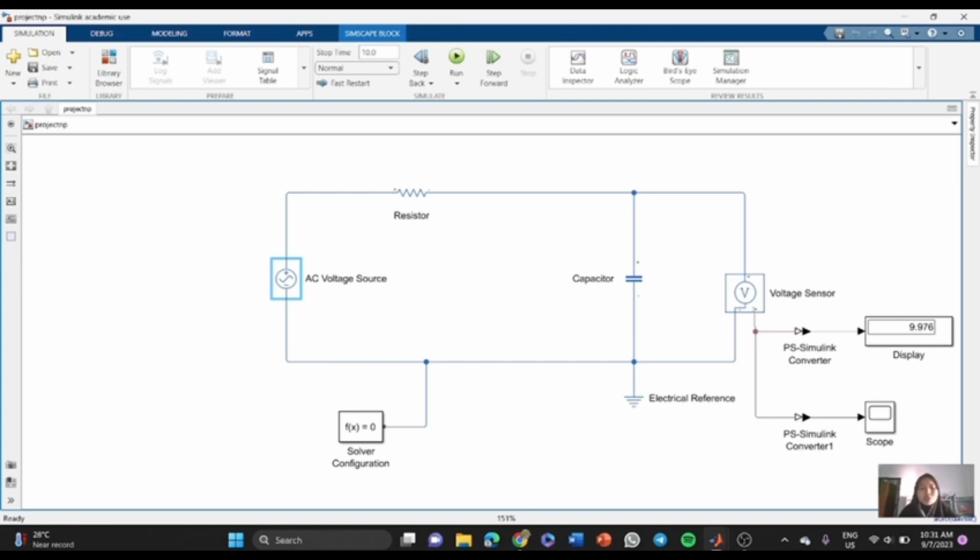Remember that a crucial component must be added while constructing the electrical circuit in simulation so that the system may do internal computation before displaying the simulation findings to us. Each physical network must be connected to exactly one block, which is known as solver configuration.